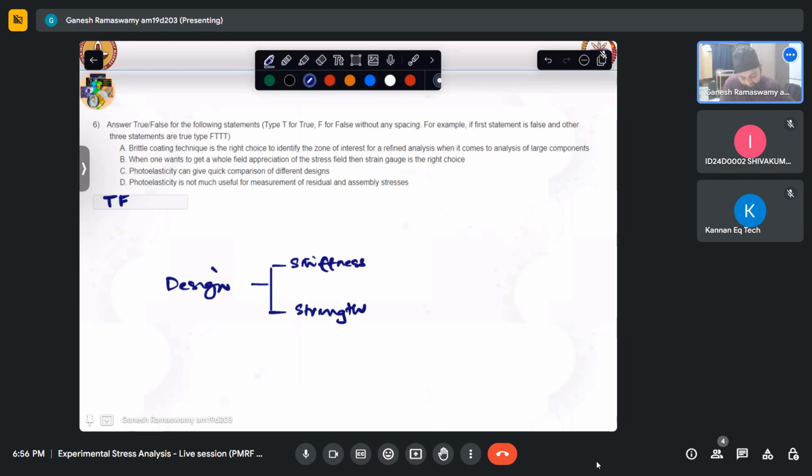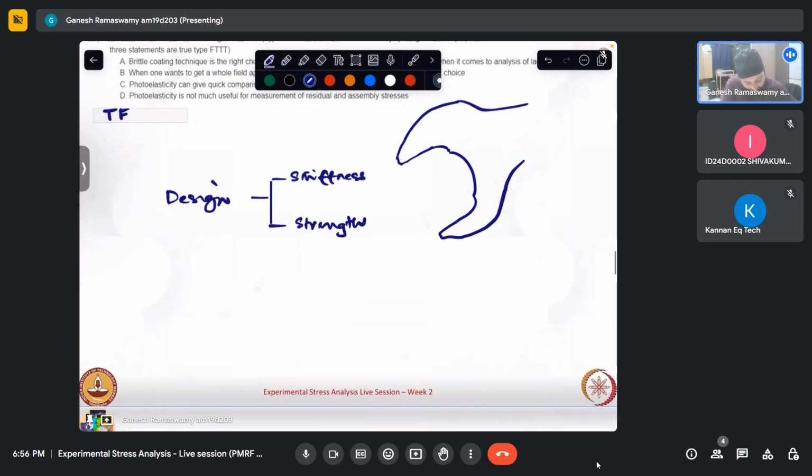So in the lecture also it is shown that if we have a spanner and if we have circular fillets like that, and in the other case this is smoothened out with a single transition curve, the fringe patterns actually show a marked change in both of these.